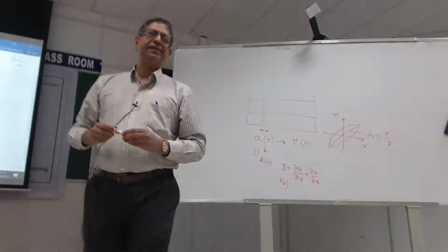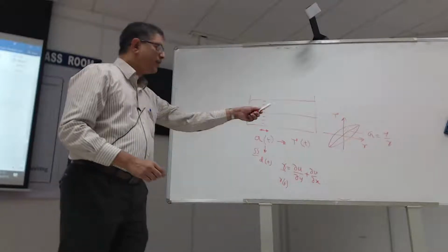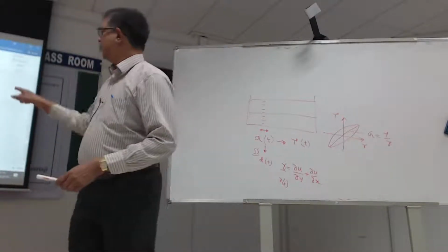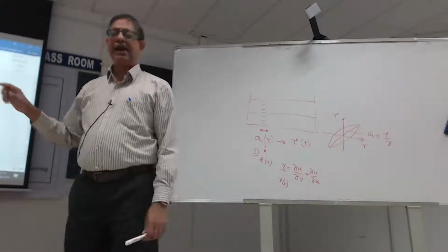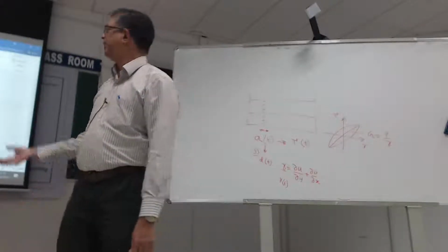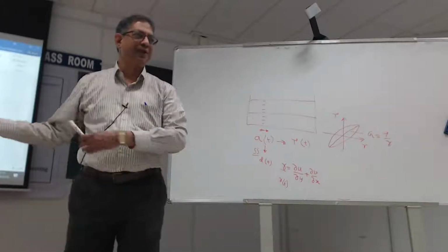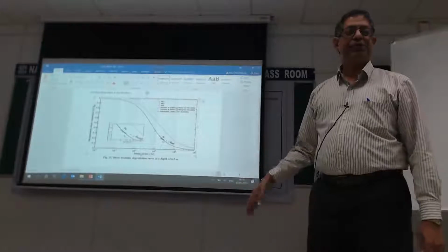We can do this for every cycle of the earthquake. Once I know the G, I can plot what the strain is and what the shear modulus is, normalized to the initial modulus. Clearly people know that these kinds of degradation curves happen. We are not the first ones; everybody in the world knows these are the shapes of the curves you get.